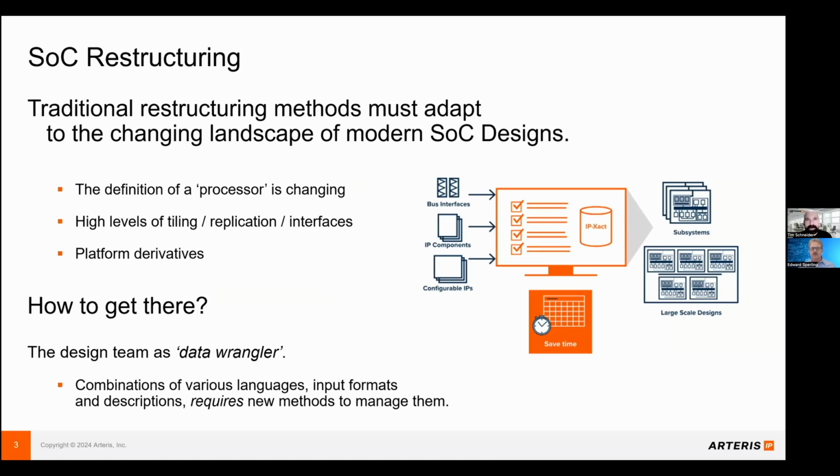One additional thing that is new in this space is IP-XACT just released a new standard through the IEEE in 2022 that is more tightly aligned with SystemVerilog. In the past, when you had SystemVerilog structs, details on ports, complicated memory maps, you could not replicate those in the IP-XACT 2009 standard. So there's a cohesion there between the standards that are starting to align that's allowing this to be more useful. So the standard caught up to what the industry needs, and the industry is finally ready to accept it, right?